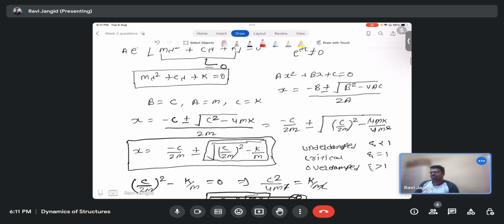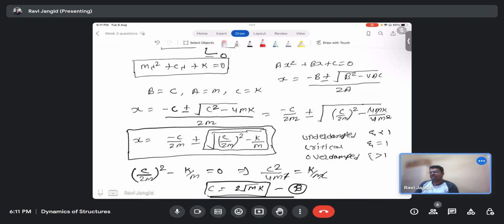so I have a question. Can anyone tell me what is the difference between an underdamped system, a critical system, and an overdamped system? Anyone? Yeah, an underdamped system means it'll keep vibrating about the axis. It will go to the positive and negative side of the y-axis or whatever x-axis we consider. Overdamped means it will not vibrate. It will gradually come to a stop.